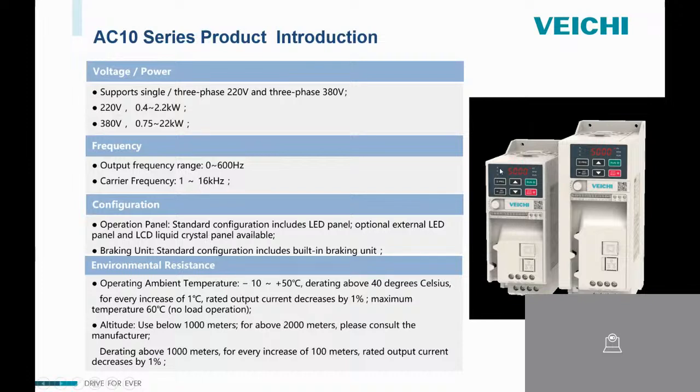And our AC10 series inverter standard configuration includes a built-in brake unit, and the ambient temperature is minus 10 degrees to plus 50 degrees Celsius, and the maximum temperature is 60 degrees Celsius, with no load operation.